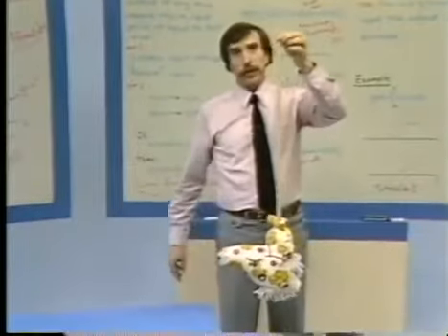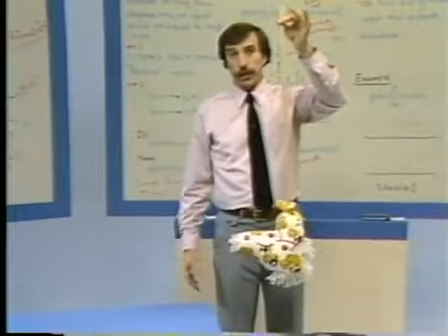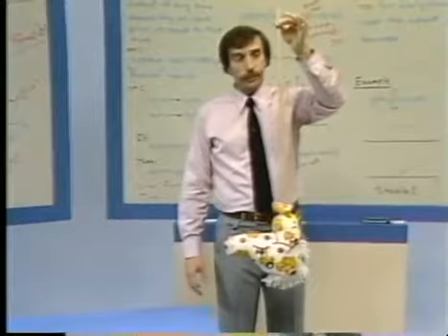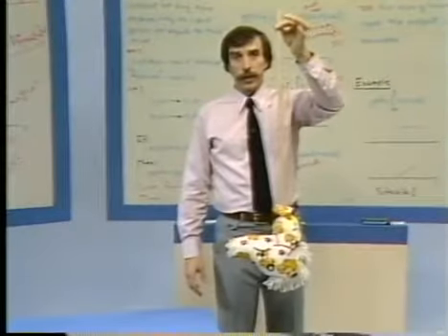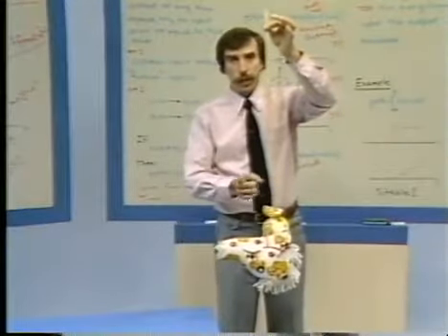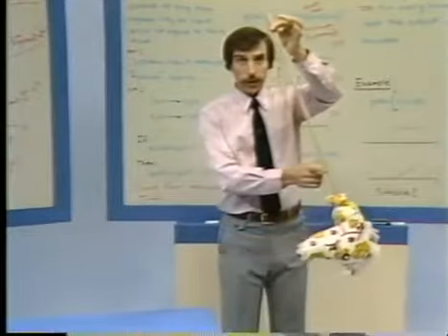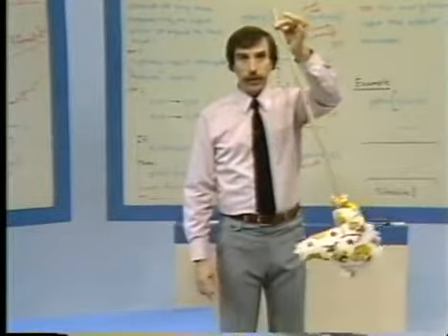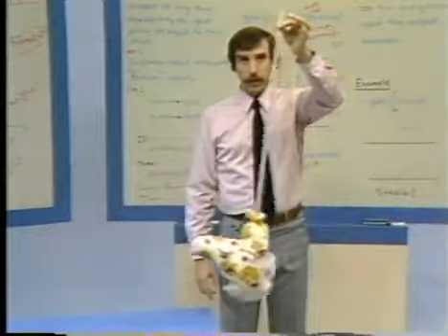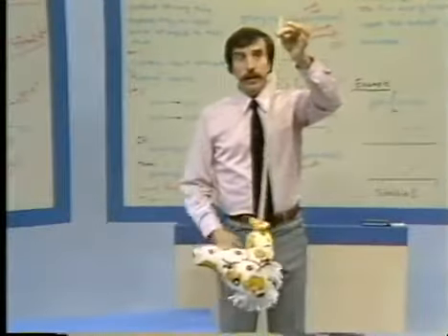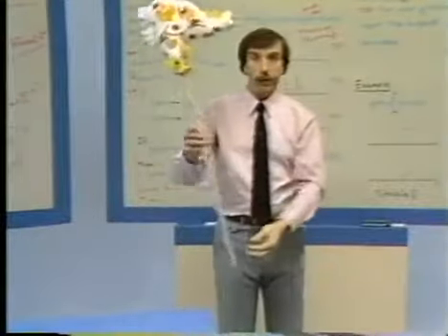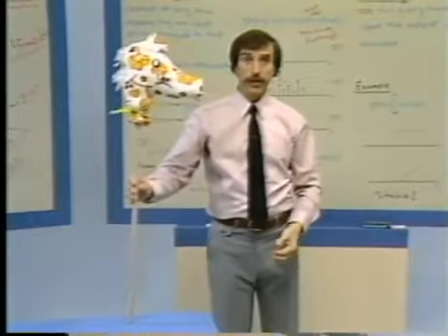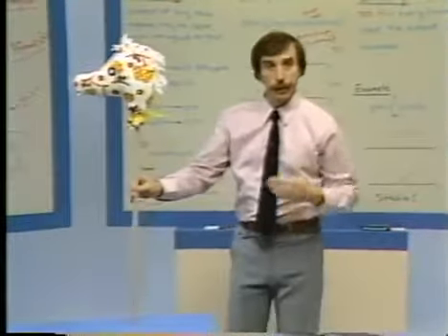If we, for example, take a system like this, which is in essence a pendulum, this system, as I'm holding it here, is stable because if I put in a bounded input, which is a displacement, the output, which is the movement of it, remains bounded. Now, on the other hand, if I put the system like this, which is, in fact, what's referred to as an inverted pendulum,